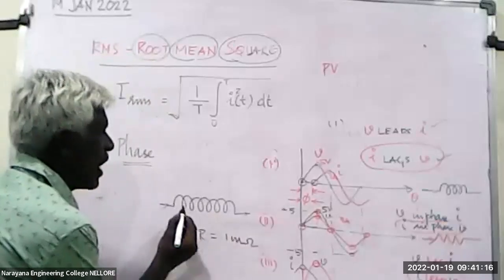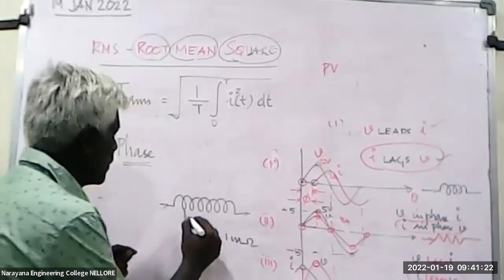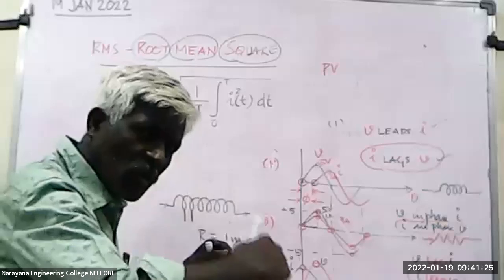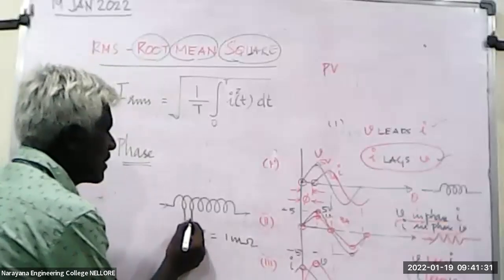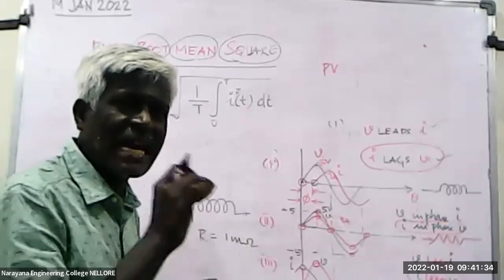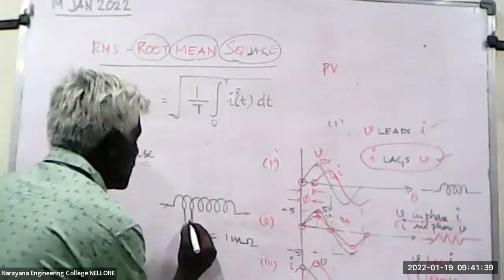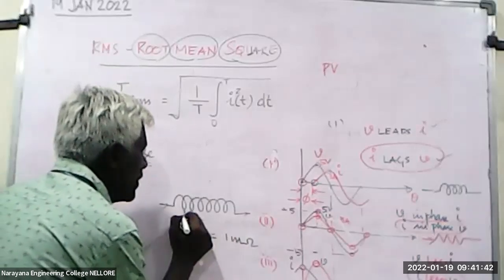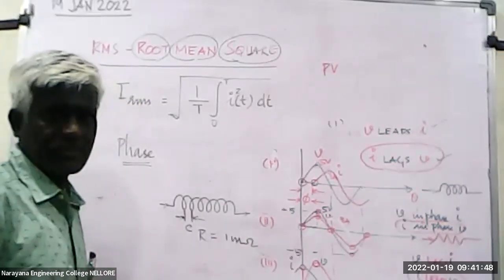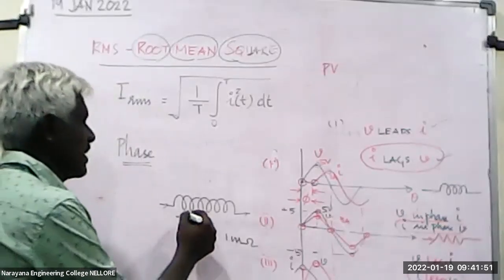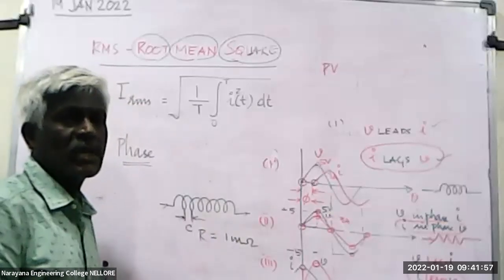Similarly, you wind the wire. This is a conductor, right? You wind one turn and another turn, and they are the conductors. In between the windings there is some air gap, and you cannot eliminate the air in between. So between these two windings we have some capacitance. So you cannot say there is a 100% pure inductor, 100% pure resistance, or 100% pure capacitance.